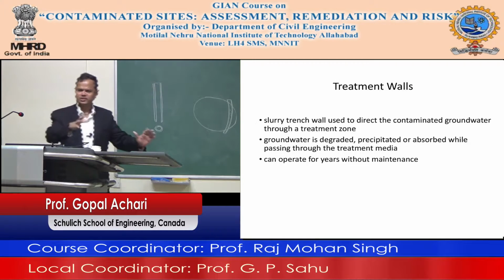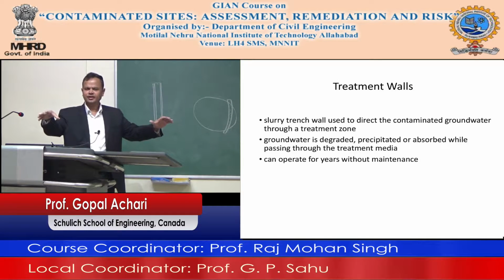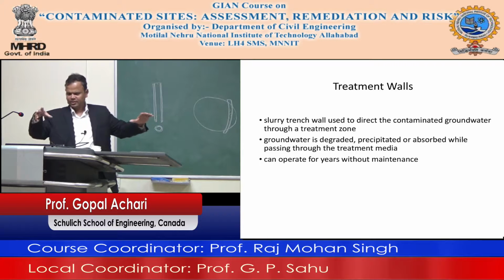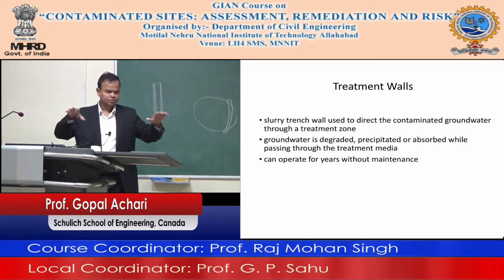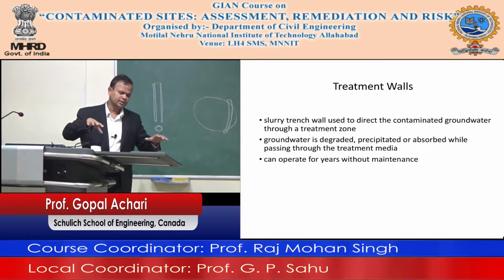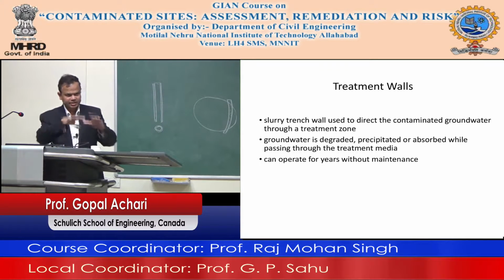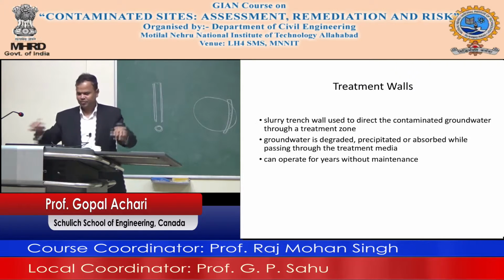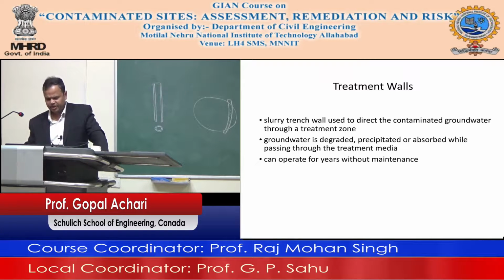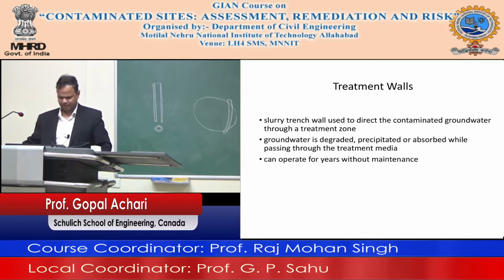So you have your waste, you cover it with a layer of geomembrane, which keeps moisture from coming inside the waste, and then you provide a drainage layer on the top, and then the top layer. Okay, pretty much that's it. This is another one of the same kind, which shows the bottom layer and the top layer. Otherwise it's nothing.